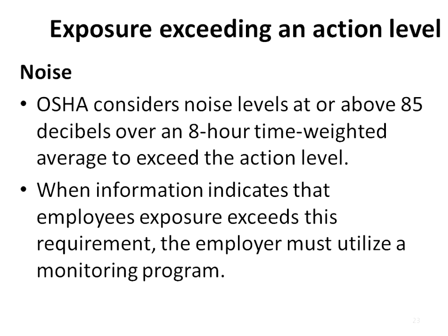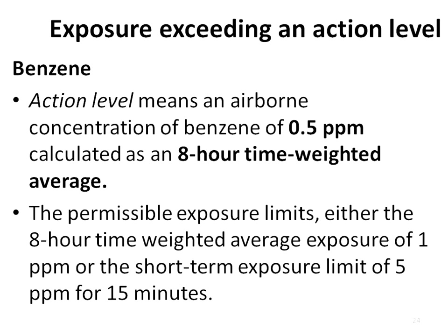So for example, OSHA considers noise levels at or above 85 decibels over an 8-hour time-weighted average to exceed the action limit. When this happens, we need to inform workers that they have exceeded the action limit, and the employer will then implement a monitoring program.